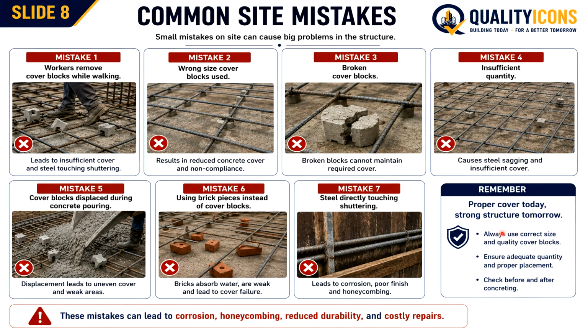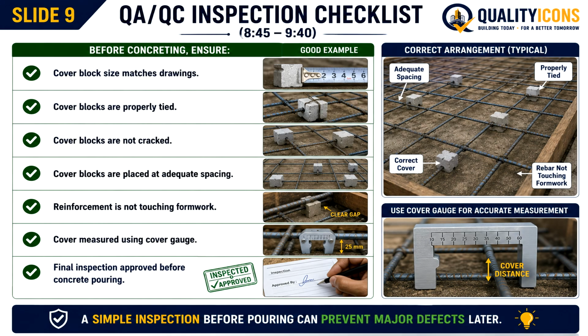Remember, proper cover today, stronger structure tomorrow. Always use the correct size and quality cover blocks. Ensure adequate quantity and proper placement. Check before and after concreting. Coming to slide number 9, the QAQC inspection checklist.